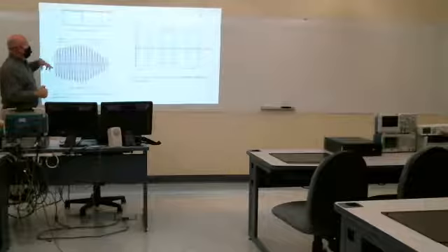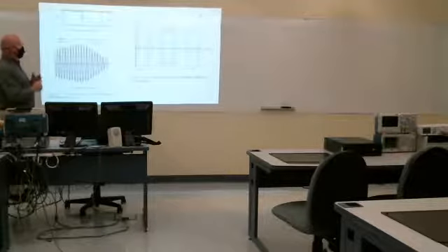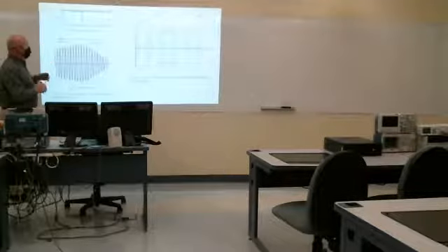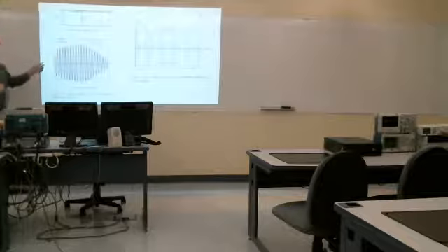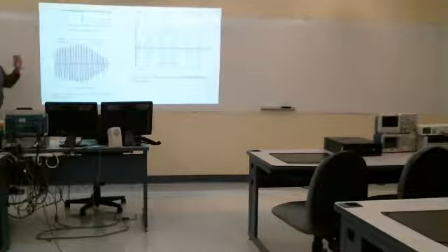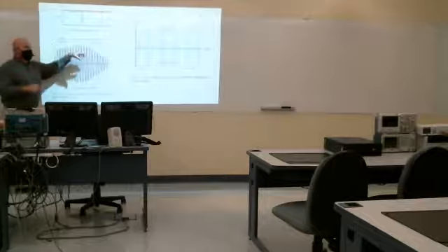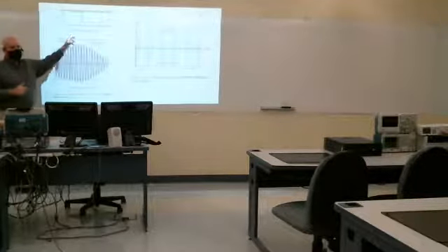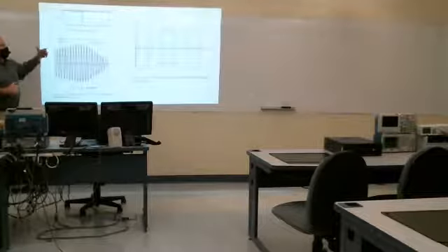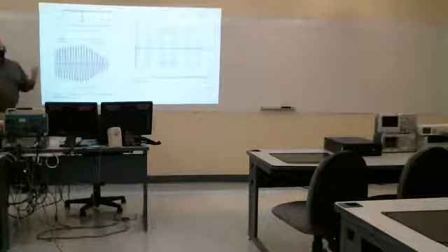But so what this allows you to do, versus the last time we looked at what an AM receiver had to do, we had to have this analog multiplier in the receiver, and we also had to recover the carrier. Those are expensive techniques. I mean, you can do that. Okay. This AM radio is just a few pennies. Okay. So this is why AM radio was so popular.